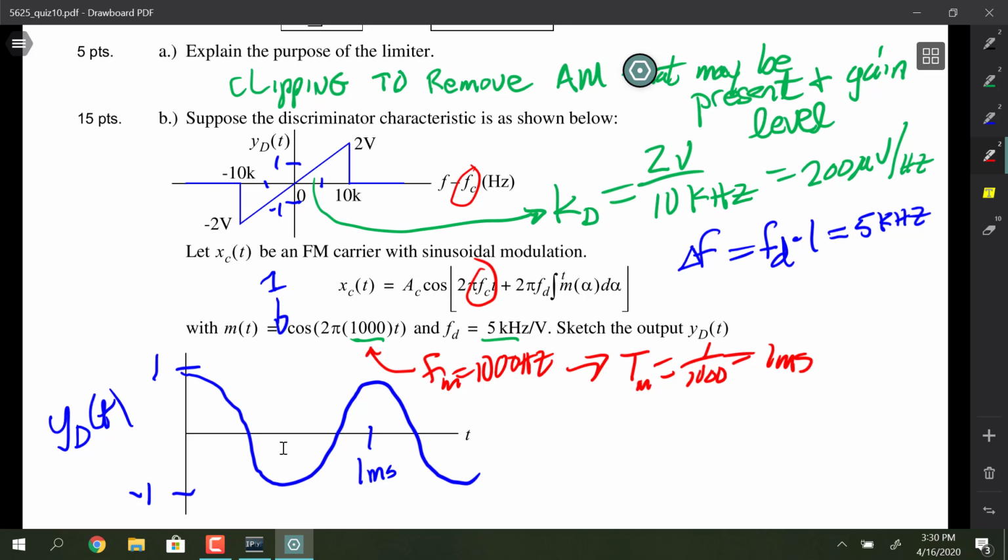And if you wanted to really know what it is, you'd have to go in there and measure it by using a sinusoidally modulated carrier and then taking a measurement with the oscilloscope on the output of the quadrature detector. And I think that's kind of where you're at in your question, John, because you were thinking analog, which is fine.